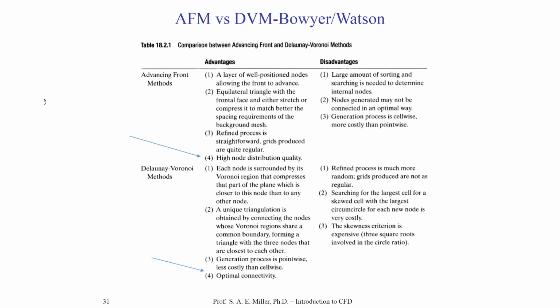Here's a table of the comparison between the advancing front methods and the Delaunay-Voronoi methods. The major advantage, of course, of the advancing front methods is that you can resolve boundary layers and put a high number of grid points in particular regions. The major advantage of the Delaunay-Voronoi methods, of course, is that they result in very optimal grid quality metrics for a particular case.